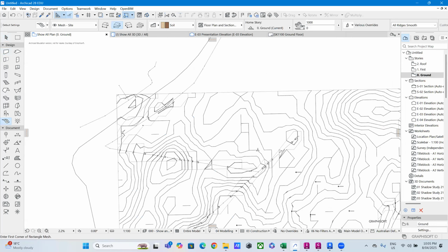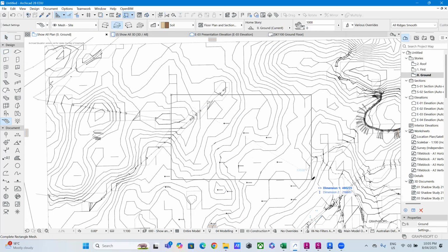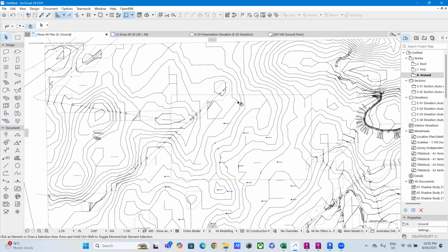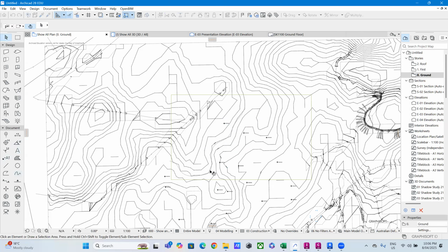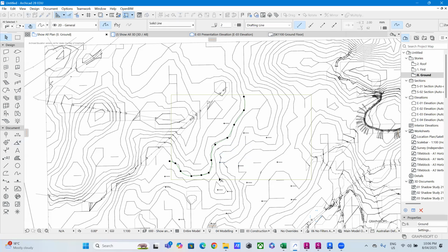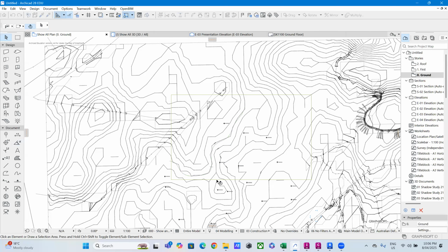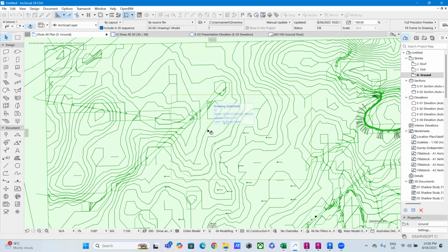In your ArchiCAD, you're able to draw your mesh, for example, like this one, and after that, start adding your control line, how it is here in the side, like this one. Okay, and after that, start adding the contour lines to your topography. I have done another video, but actually you need to click on this one and start adding each contour to your topography. See it in the other video.